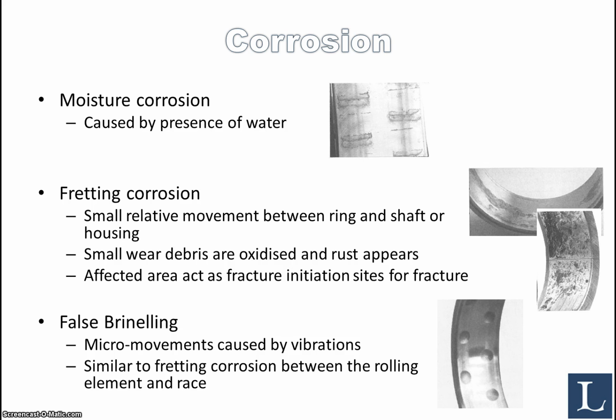The micro movements will then cause some small initial adhesive wear. The particles will be retained in the contact, and basically what you will cause is small indents in the bearing, and these indents will then act as initiation sites for fatigue damage.